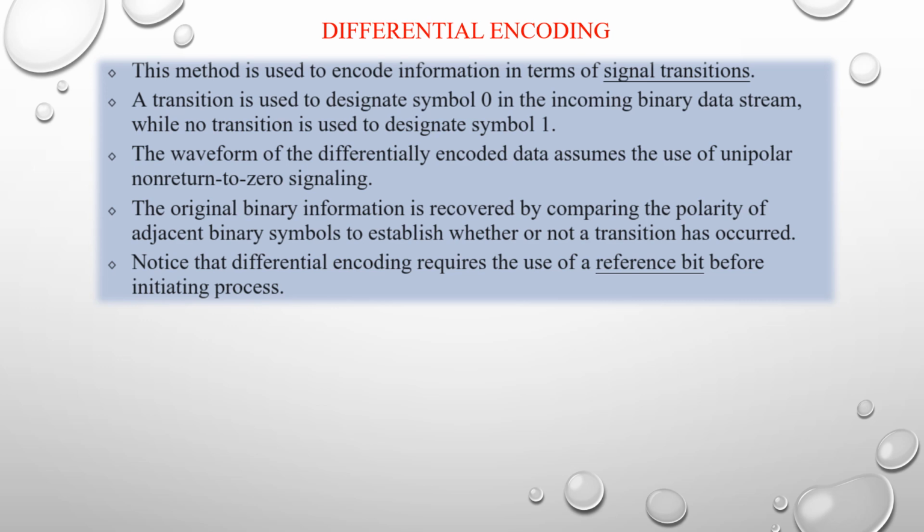The original binary information is recovered by comparing the polarity of the adjacent binary symbols to establish whether or not a transition has occurred. Notice that differential encoding requires a reference bit. It requires the reference bit before the initial process.